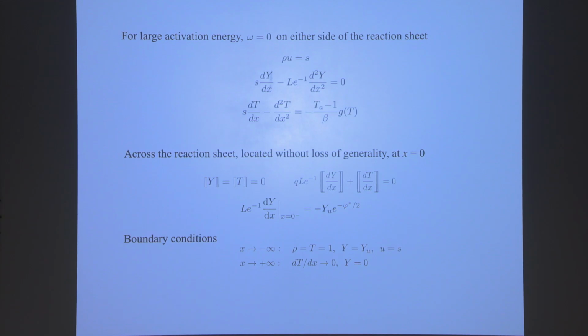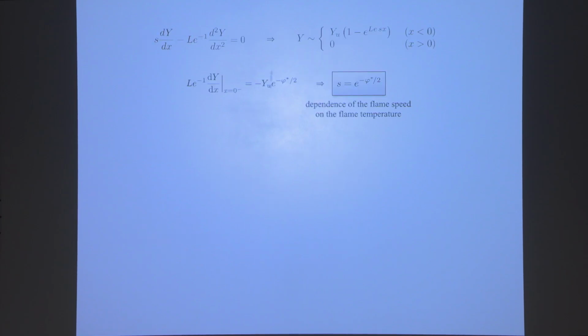Or more accurately, deviation of flame temperature from adiabatic, and deviation of flame speed, or fractional flame speed, from the laminar flame speed. Those are the two unknowns in this mathematical model. Other than that, this is a complete, consistent mathematical model that needs to be solved.